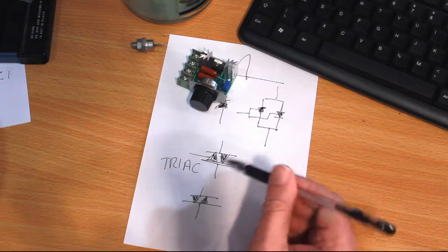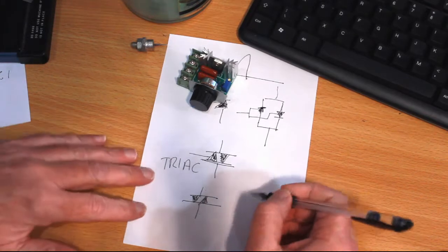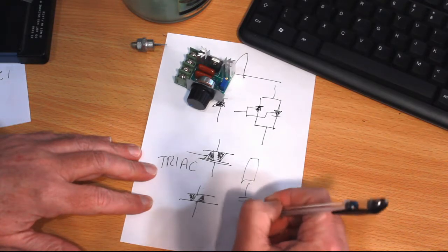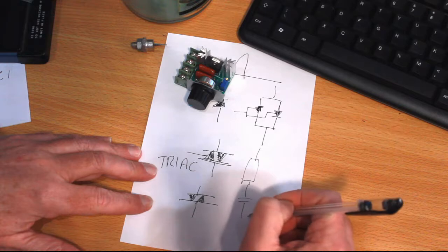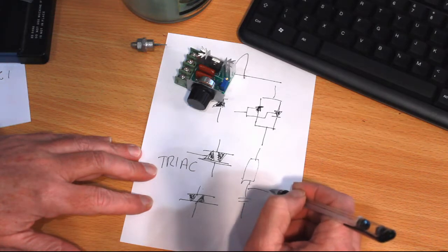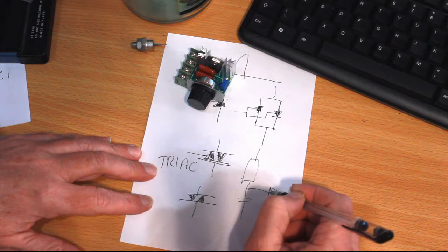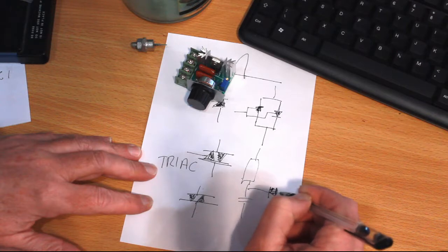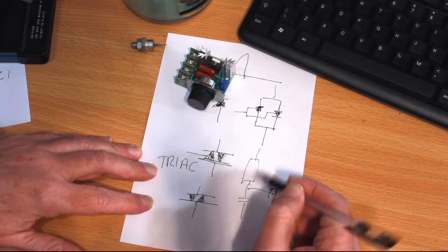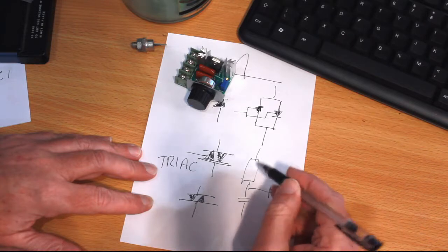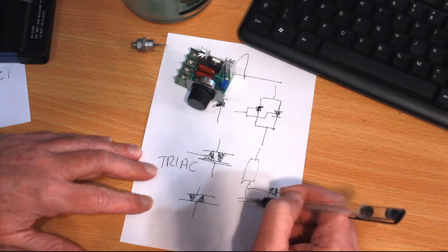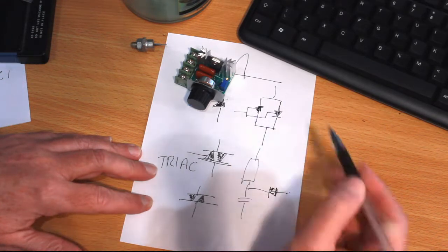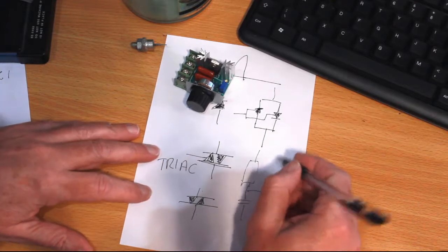In fact, the whole dimmer is. So when you get to a certain point in the phase, this one uses a resistor capacitive network to charge the diac. Okay, we'll do it that way. There we are. Just do a W. That's the easiest way. Diac there. The charging of the capacitors controlled by the resistor. When it gets to a certain point, that conducts, pulses the gate on the triac.